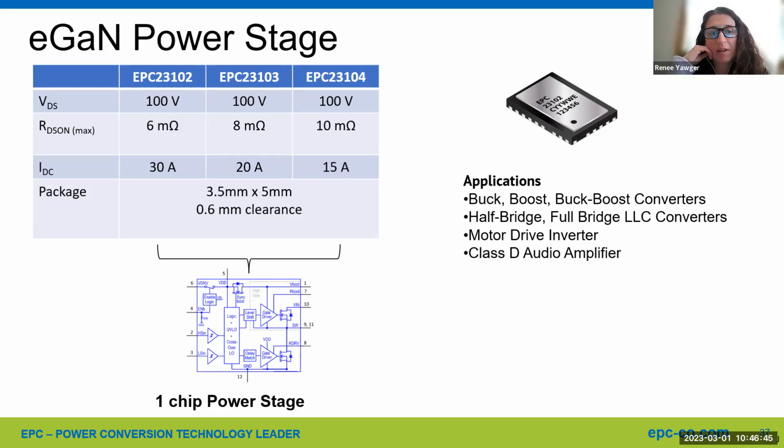So I have a design, my ideal output voltage is around 12 volts. Is there more information about efficiency versus input voltage? I guess it depends on the particular board. Some of the boards and some of the controllers from different companies have graphs at different input voltages. We tend to use 48 volts as an input to 12 volts to show that as a typical situation.